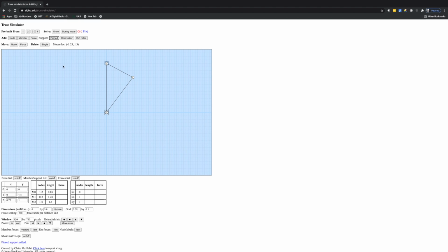Okay, so I've got the supports, and now I just add a force. We need to add the force in this case at node 2, which corresponded to our joint C from example 1. So I just click on this for a certain direction here, and you notice it put minus 50, but really we wanted minus 2.8.